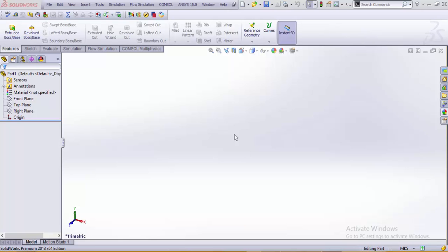Even though the contact is a line, a knife edge or flat faced follower usually produces a higher amount of friction. So we try to go for rollers or spherical faced ones. According to the path of the motion of the follower, they can be divided into mainly two categories, radial followers and offset followers. They are defined for specific motions like simple harmonic motion or oscillating motions.